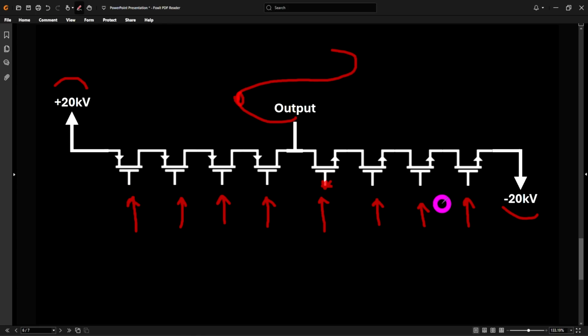So the biasing network that sits over here and applies the input signal to all of these now becomes considerably more complex. By the way, this stacking architecture is used inside semiconductor transistors to build power amplifiers too, even at millimeter wave and higher frequencies. It's a common architecture. Here, we're dealing with a much harder problem because of the high voltages.